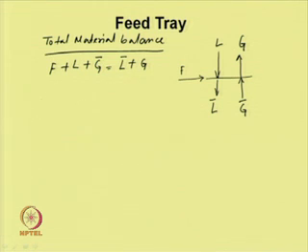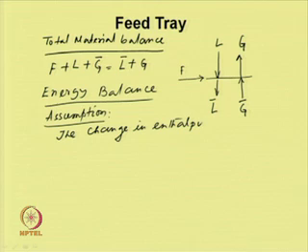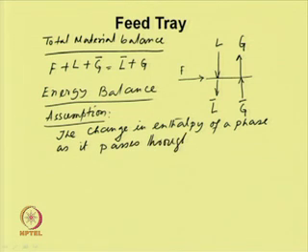Now, if we do the energy balance, we can take the assumption that the change in enthalpy of a phase as it passes through the feed plate is small.